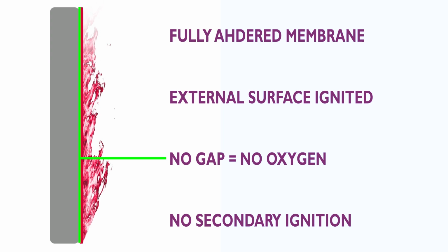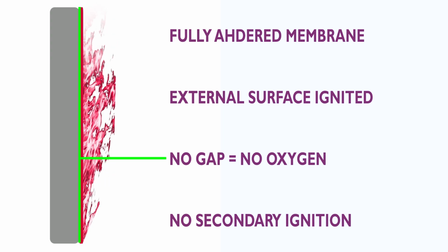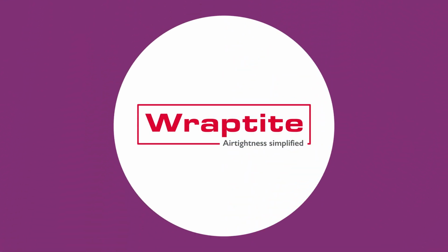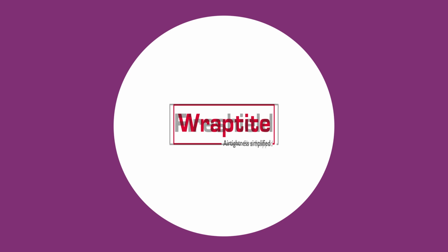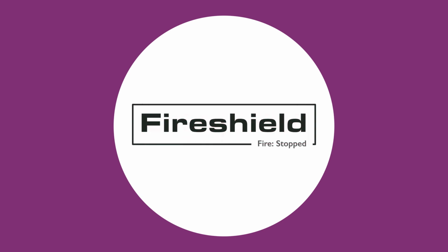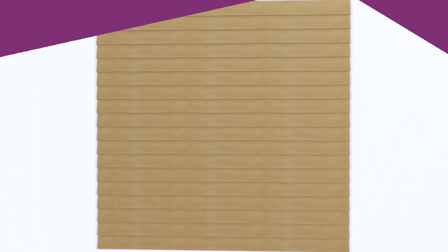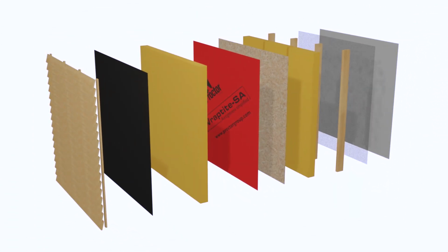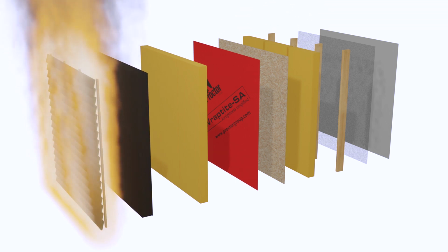So, we've looked at how the Wraptite membrane reacts to fire and how it complies with the relevant technical standards. But if we want to go beyond fire resistance and introduce a degree of fire protection, then another option is to use the Fireshield membrane. Fireshield is a vapour permeable membrane with a unique surface composition which actively reacts to prevent fire taking hold. Fireshield can be used over insulation boards to provide an additional layer of fire protection to the internal structure of the building.